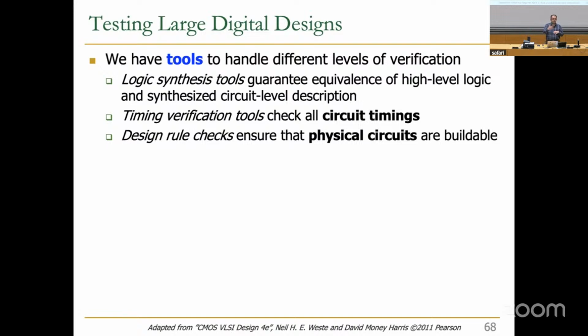When you input your HDL code and it is synthesizable, then your gate-level output has exactly the logic that you are looking for. But for timing verification, you need to use other tools, and these tools check all circuit timings. There are also design rule checks to ensure that physical circuits are buildable, essentially.